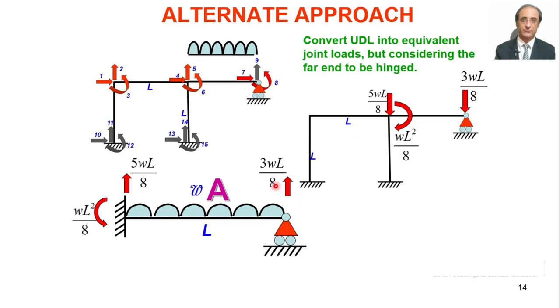So here in the case of structure A, we are considering the end as hinge, and same is considered when we are analyzing structure B. So the resultant, when we superimpose, that will also be a hinge. So here by these, the final member end moment at this will be 0 automatically. So here in this particular case, our components of the load vector will be like this.